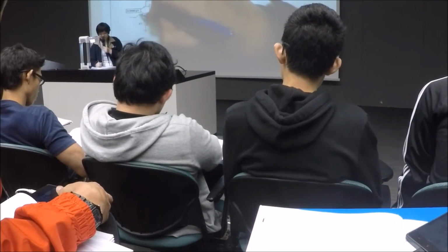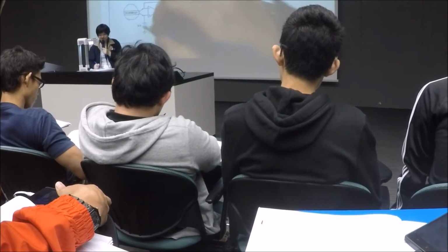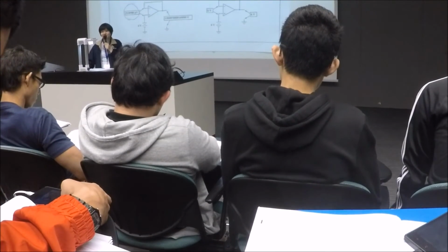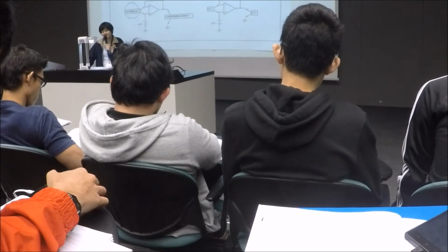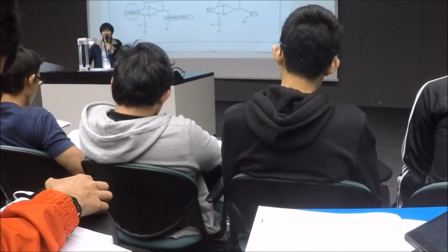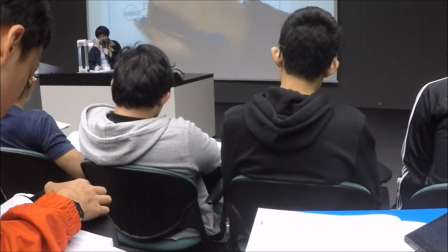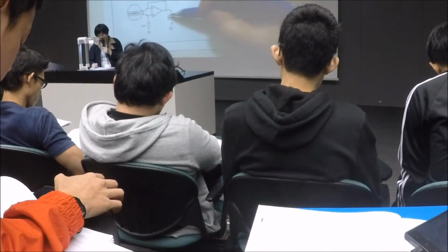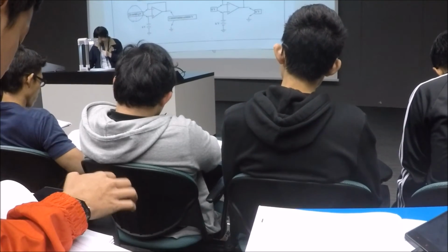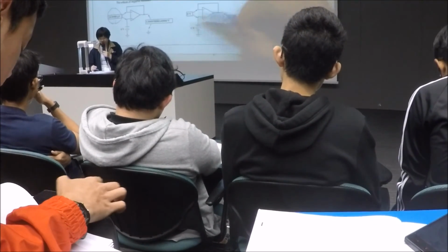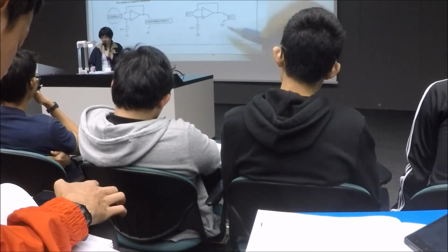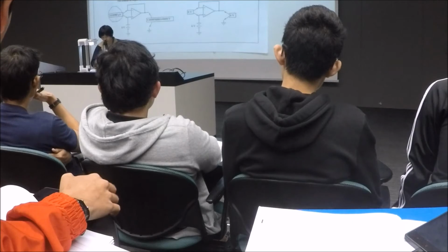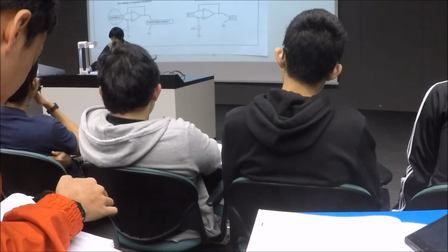The reason you see some difference here is that the gain is not infinite, so it has some finite value. So there is some drift here, but comparably and approximately they are equivalent. If you do some rounding off, of course, you can get exactly the same voltage. Compared to 6 volts, 29 microvolts is extremely small.